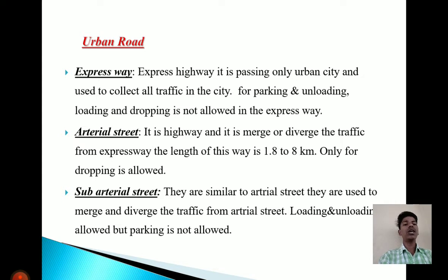Subarterial street is similar to arterial street. Its function is to merge or diverge the traffic from the arterial street. The arterial street merges or diverts the traffic from the expressway, then the subarterial street merges or diverts the traffic from the arterial street. In the subarterial street, loading and unloading are allowed, but parking is not allowed.